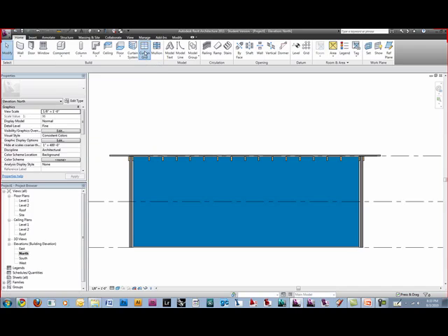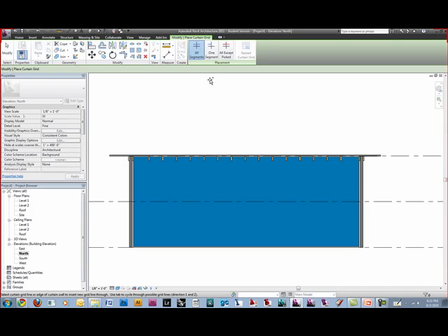But anyway, so curtain grids, click that. And now you see you have a few options here. You have all segments, which will give us one full line across and cut it completely in half, or we have one segment. Now one segment, if you have no grids there to start with, then this is just one segment. But let's say we placed this grid first, so we sort of cut it right in the center here, 10 feet, 10 feet. And then we went to one segment. It'll only go on one side of it versus both sides. So here you see it on the bottom side, or we can do the top side. If we do all segments, it'll just cut all the way straight through.